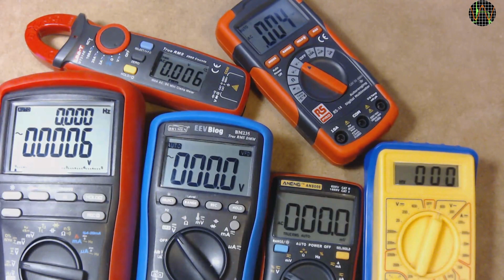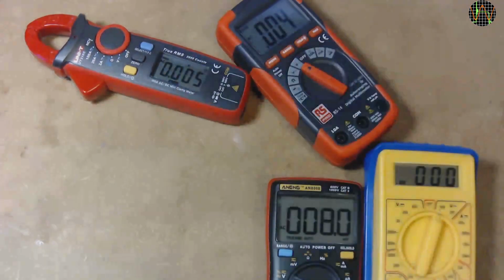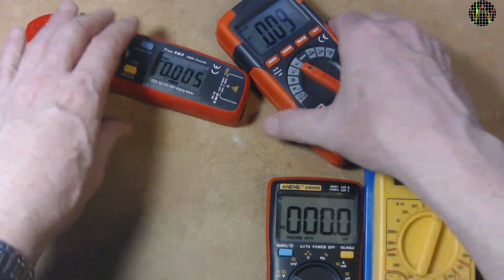Well, that's it for this video, and I have had quite enough of true RMS and averaging meters. But I encourage you to have a play with the waveform analyzer spreadsheet. While true RMS meters manage to display the correct AC True RMS in all these tests, averaging meters only work correctly for sine waveforms. For square and pulse waveforms, you may be able to correct their readout if you know the duty cycle. That begs the question, why bother with averaging meters at all?